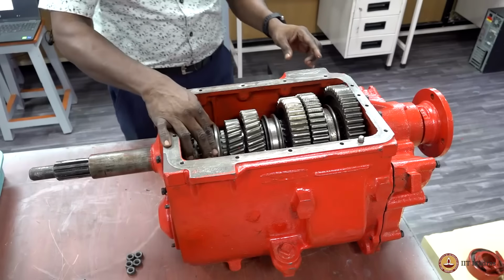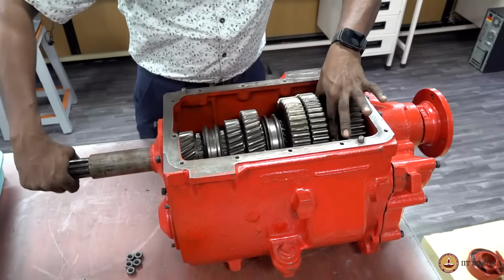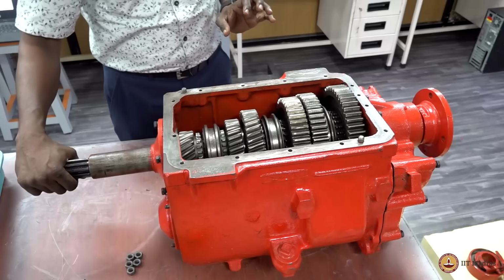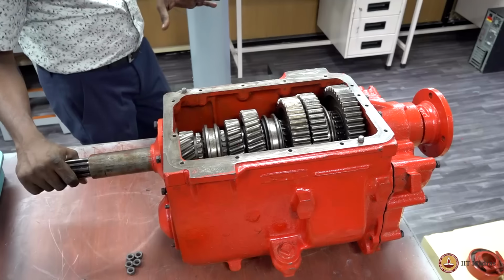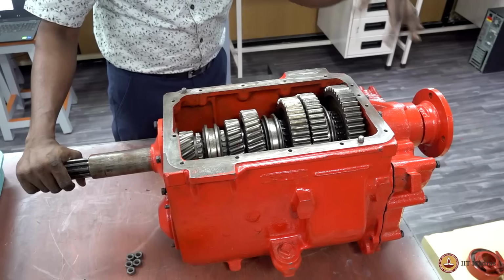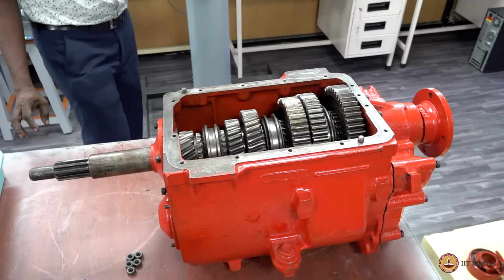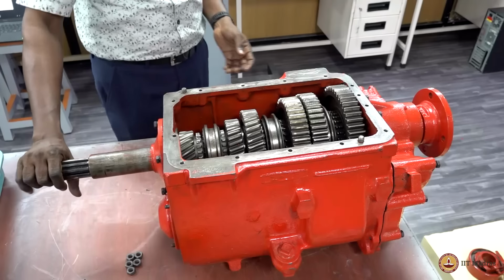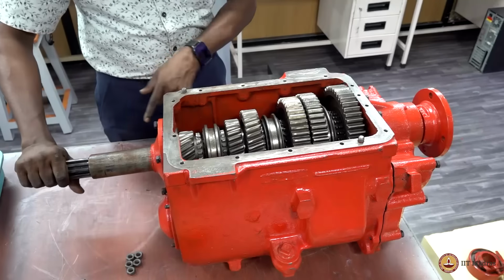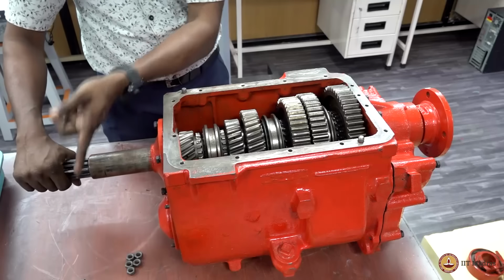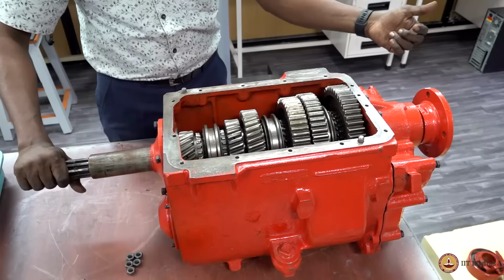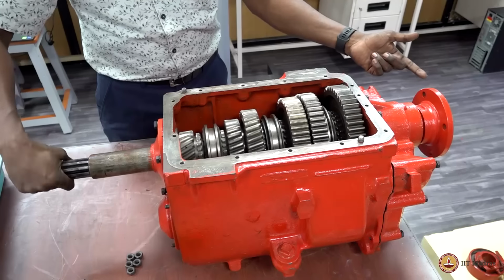Now I am going to engage the reverse gear. Now I engage the reverse gear. In reverse gear, we have to observe 2 things. One is the flange has to rotate in the opposite direction, as well as it has to maintain the 6.6, almost 6.5 revolutions of input shaft turn. Now I start. Now I turn the shaft in this direction, but the flange is going this way. So the reverse gear is engaged.